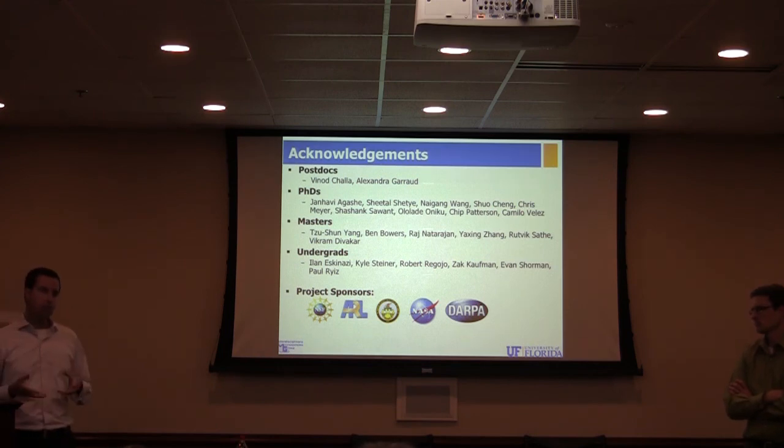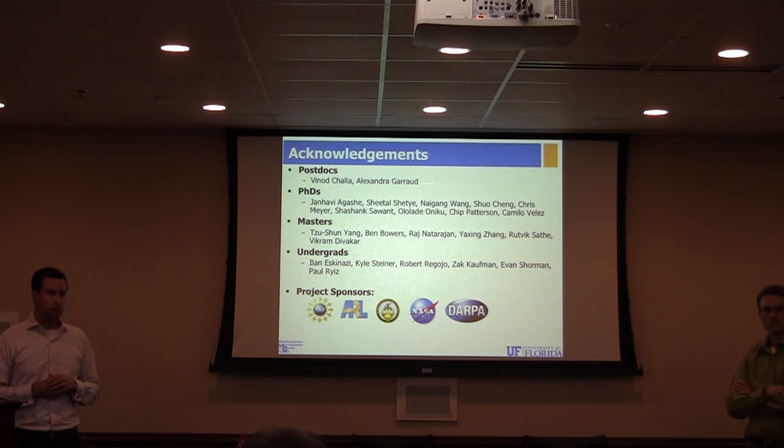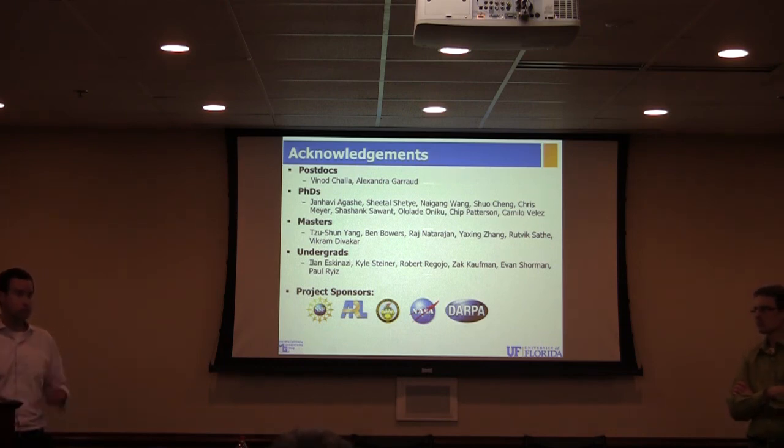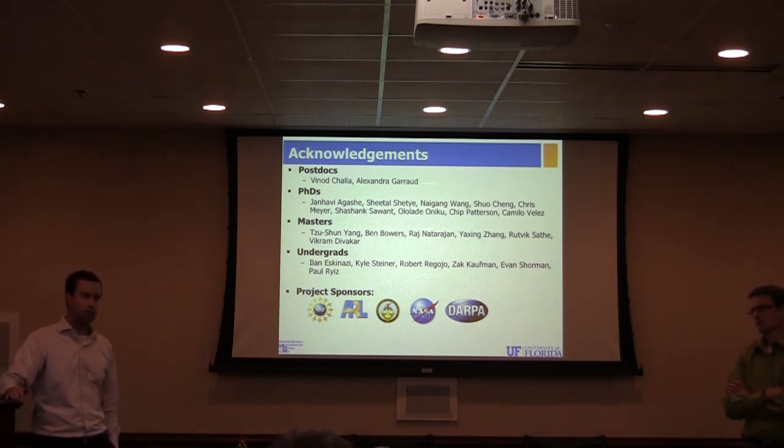The biggest challenge is to actually get a high volume fraction of magnet. This comes down to control over the particle morphology and the monodispersity of the particle sizes, and there are different tricks and games you can play. We haven't exploited that fully, but to get good performing magnets, you try to get a high loading fraction. The typical numbers we get are 50 to 70% by volume, and that's pretty good for most applications. So we're achieving 50 to 70% of the remnant magnetization, or the potential magnetization, the total moment of that.